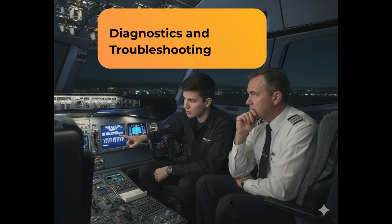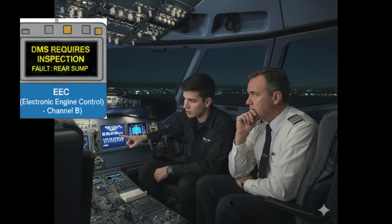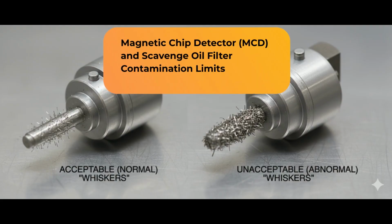Diagnostics and troubleshooting. The system serves as a critical reference for both pilots and technicians for fault isolation and diagnosis. Upon receiving a maintenance required message, the pilot or technician can access the relevant pages on the flight management system display in the cockpit to identify the specific source of the debris, whether it originates from a specific sump or a gearbox.